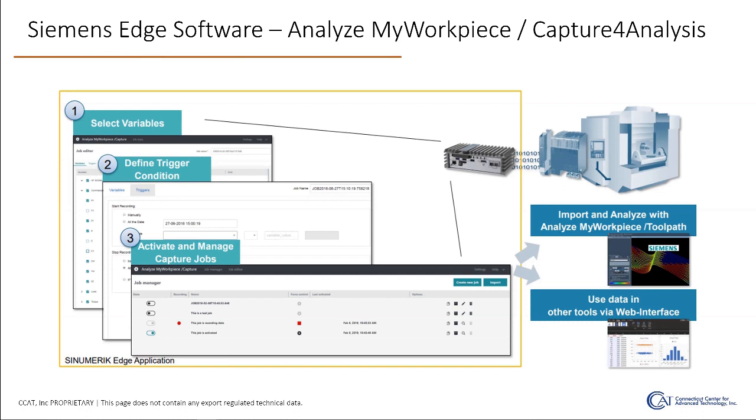So in our case, what we did was we added trigger phrases as comments in the NC code itself. We would put start rec, and then after that the manufacturing operation number. In this case, we didn't put the feature ID because we had the mapping file. What the Edge device does is, when you're cutting the part and it gets to that line of code, it triggers the Edge device to start the recording process. For stopping the recording, we put another trigger phrase in the NC code as stop rec. When it hits that line of code, it stops the recording process.